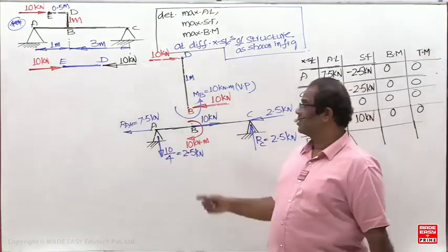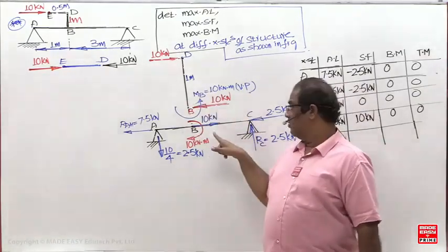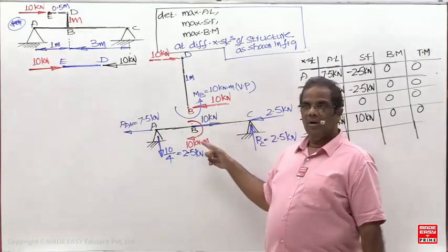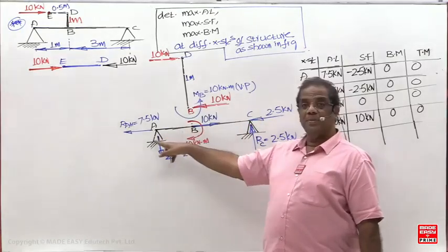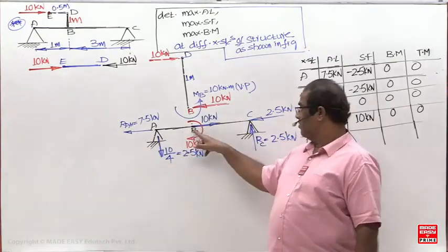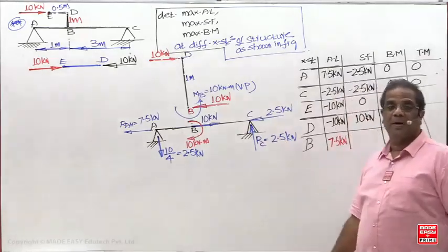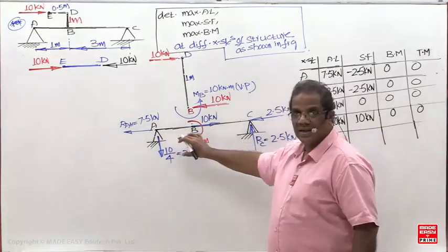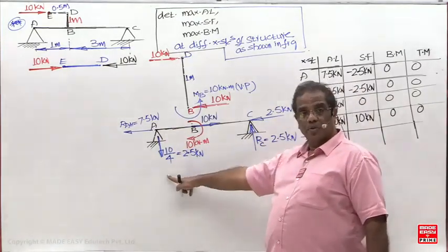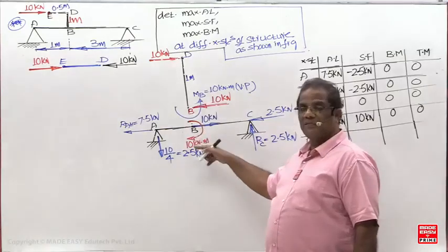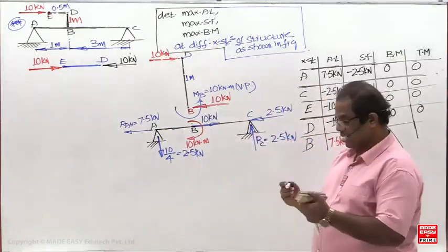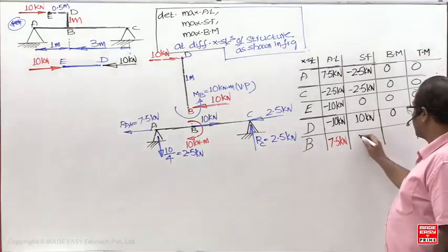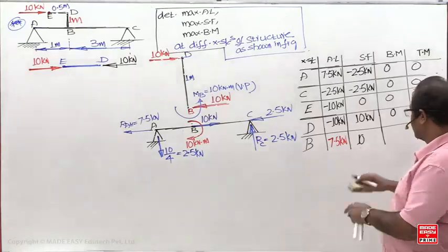Next, what about the shear force? Directly the shear force. Here how many times do you have to calculate? Only one time. It has only one shear force. So when B belongs to BA, what is the shear force? Minus 2.5. When B belongs to BC, what is the shear force? Minus 2.5. So what is the larger value? Here 10. Here SFD is constant, shear force is constant. So here shear force is 2.5 minus, therefore here also minus 2.5, here also minus 2.5. So what is the shear force value now, larger of plus 10 and minus 2.5? So plus 10.